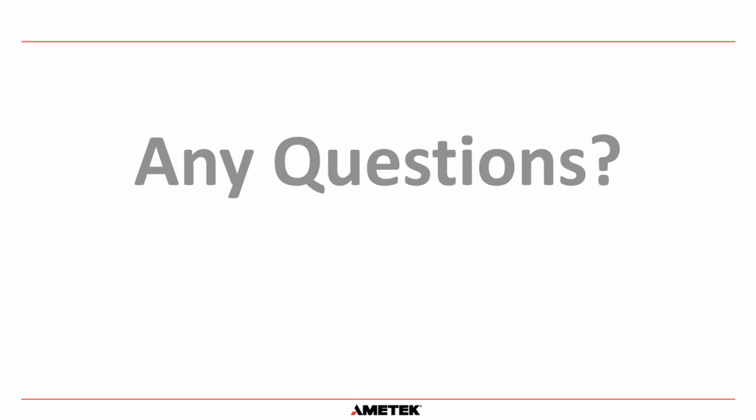And how do we know if the end user is being supplied by an HRG system? Yes, you are supposed to always ask that question at the design stage. One of the first questions, if you are an EPC, or an engineer who is designing a UPS for a plant that you've never been to before, is: do you have a high resistance ground system?